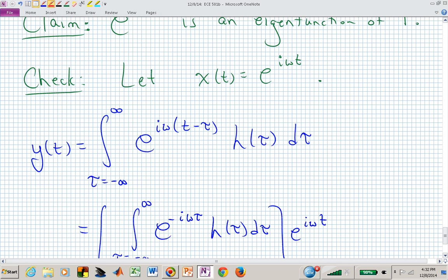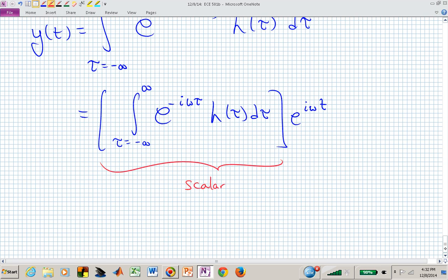So we have this system where we applied an operator, which is this convolution operator. We used that operator on this input, x of t, and the result ended up in the same direction, in the same eigenfunction that we started with, e to the i omega t. This remains our eigenfunction, which is now scaled by some scalar. And that is then giving us our output y of t.